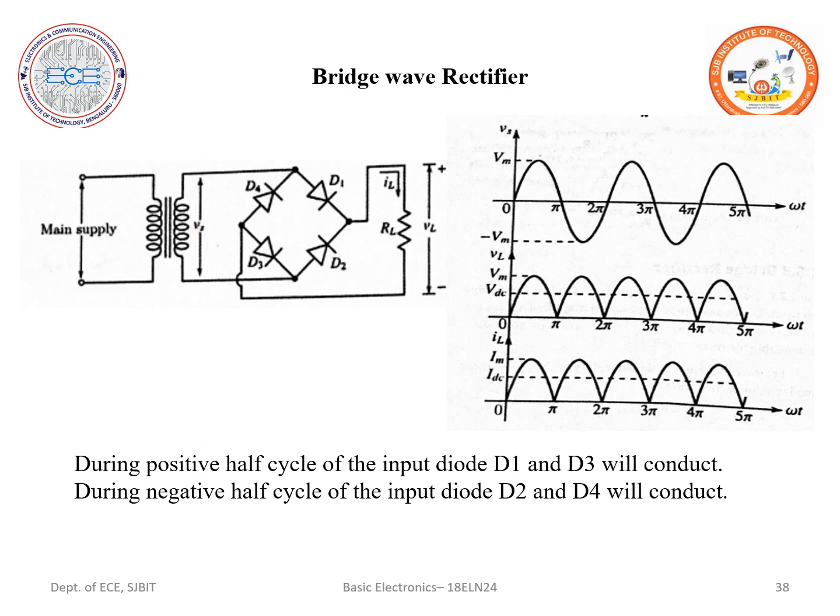The polarities across the point, let me name this point as A or the node as A and this as B. Now, once the positive cycle is applied here, I can say the polarities across the secondary winding are going to be positive and negative, as shown here. Now, once point A is positive, can I not say my diode D1 is now in the forward bias condition?